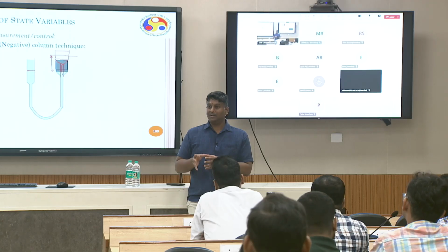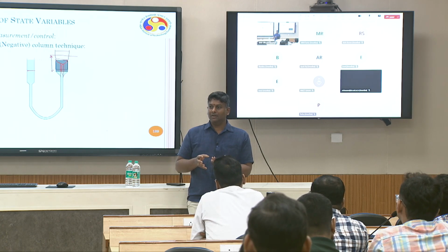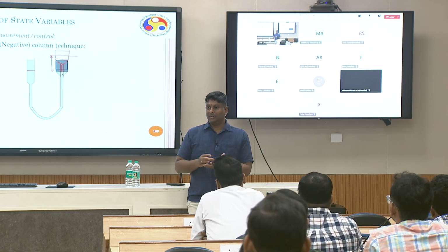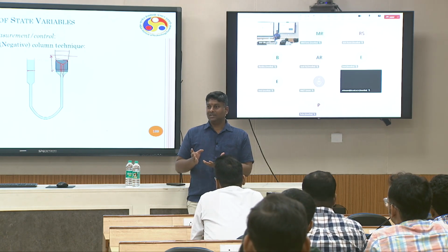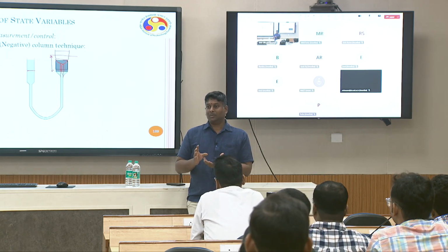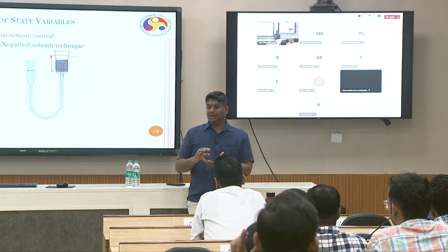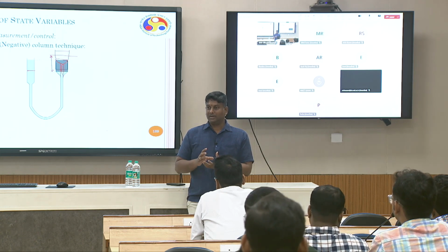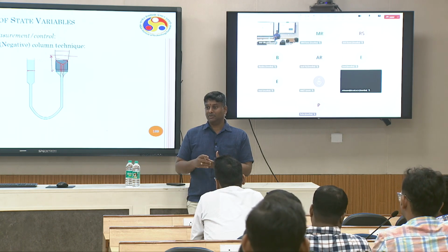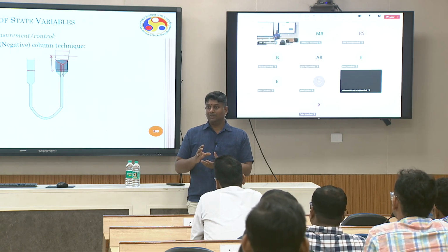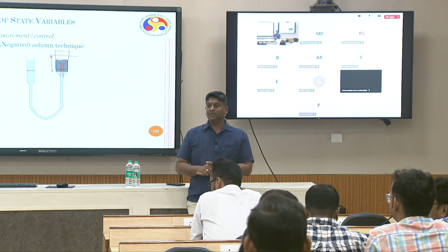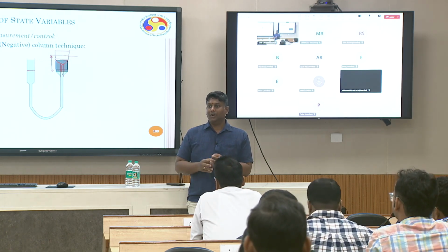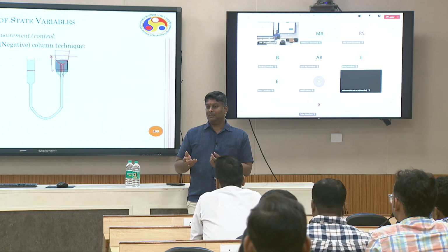In fact, we could estimate for compacted bentonite. Powder bentonite also we did, and compacted bentonite of different quality, where the specific surface area went up to nearly 600-700 meter square per gram. For those clays in a compacted system up to 1.7 gram per centimeter cube dry density, we estimated the entire SWCC curves using different techniques, osmotic and vapor equilibrium, etc.